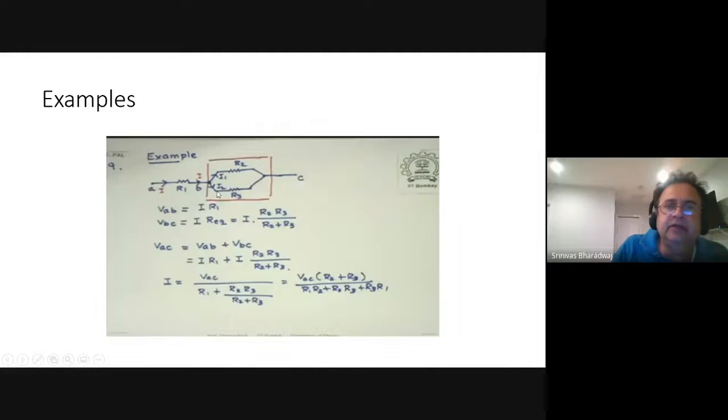BC, right? So the voltage across BC will be I times REQ, where I is the total current flowing through here. So I times REQ will equal the voltage across BC. Okay, and so that's how you can solve it. The other way is to say I equals I1 plus I2, and then you introduce a second variable.